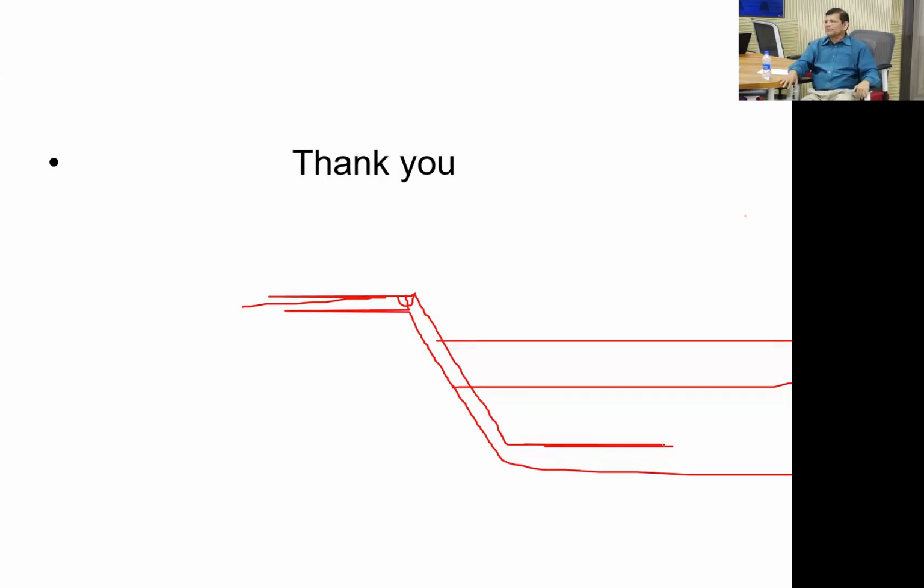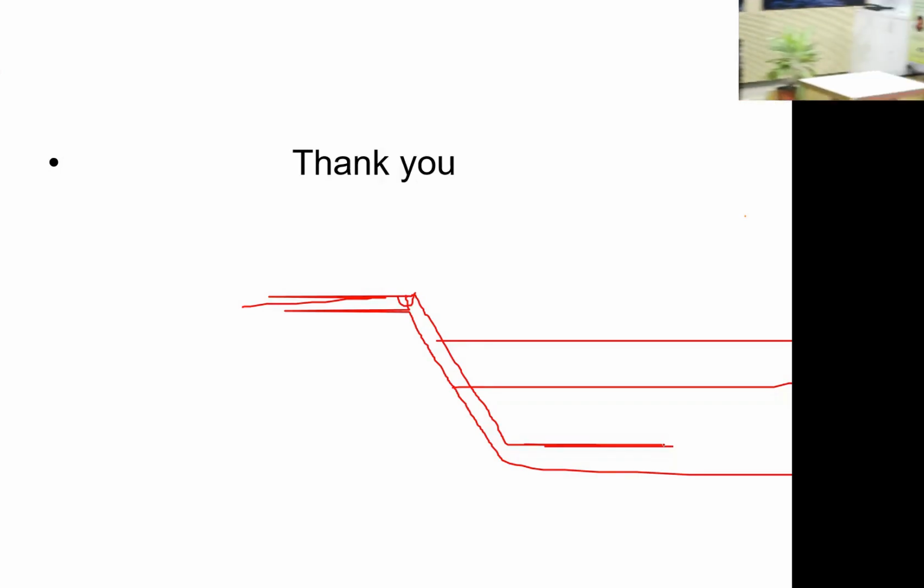Whenever there is a liner, you have to assume there can be a crack or puncture in the liner, and the water coming inside the dike will be drained out. Just to keep the dike dry, they have put that. Otherwise there is no use. Some designers provide a vertical liner at the middle of the dike cross section. Vertical liner, core liner.